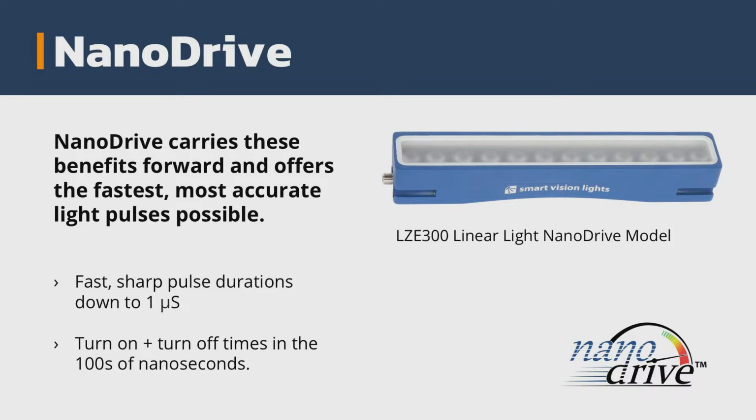One, you can have minimum pulses down to about 1 microsecond. So the light will turn on and turn off within 1 microsecond and give you a very short, bright overdrive flash. Whereas in our standard products, the minimum time was about 10 microseconds. The other thing that happens as you get these very short pulses is you need them to be accurate. In the standard products, even with overdrive, there's a few microseconds of latency, and then more than that, there is a few microseconds of turn-on time as we turn the light on.